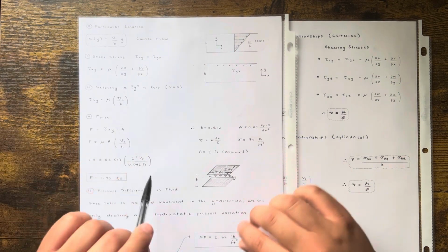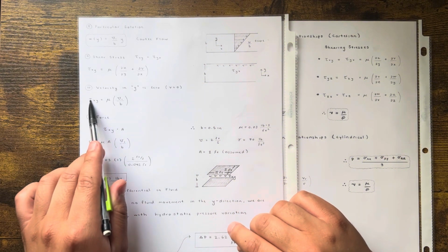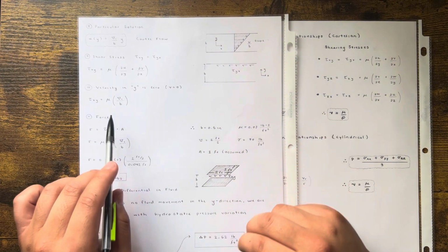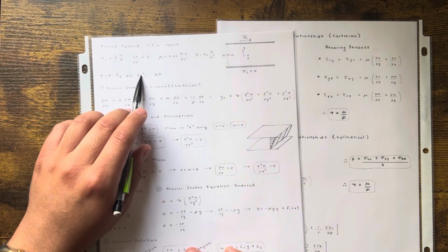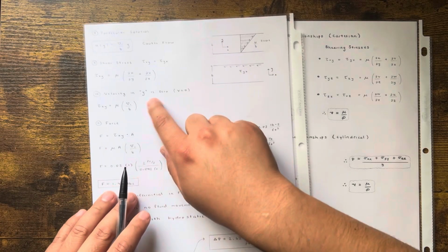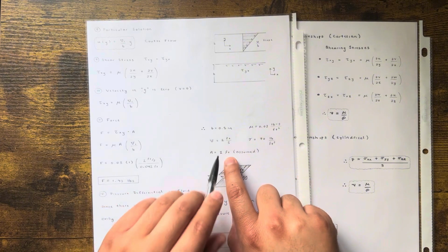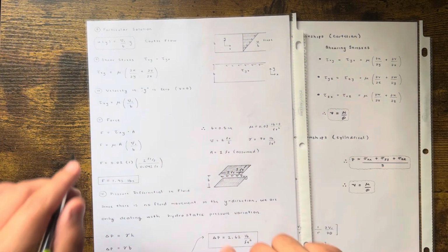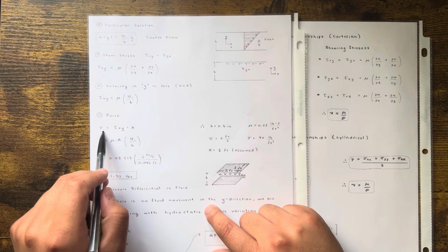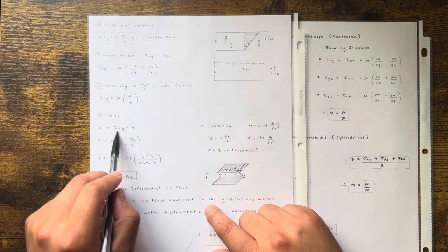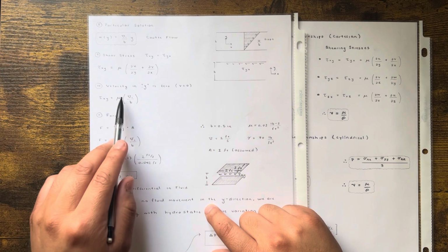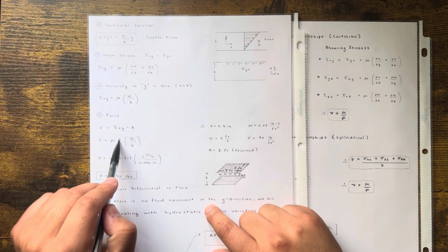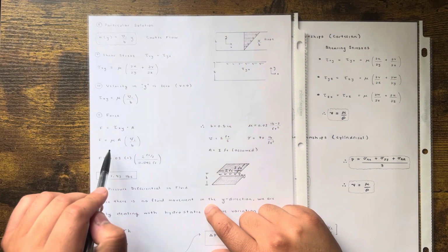So now that I have U1 over B, I have to multiply this times area to get me force, right? Well, they don't give us an area of the plates. They just say they're infinite plates, but they want it per unit length, per feet squared, right? So we know area is just feet squared. That's why on area, I assumed 1 foot. Okay, just keep it simple. You don't have to do anything crazy. So in that case, I'm just going to plug in Txy for force. Txy times area. I plug in mu. I just added an A in the middle right here, and that's 1 anyway, so I'm really just solving for Txy.